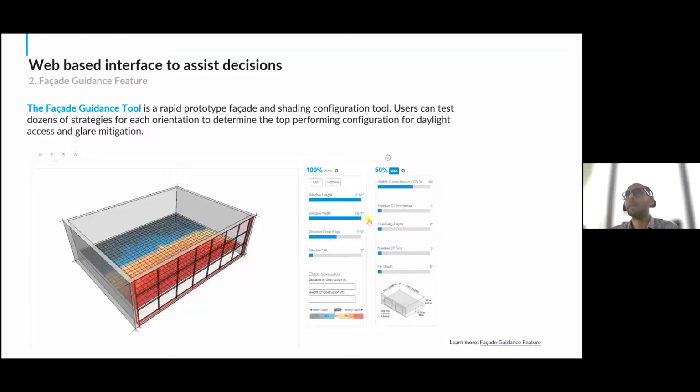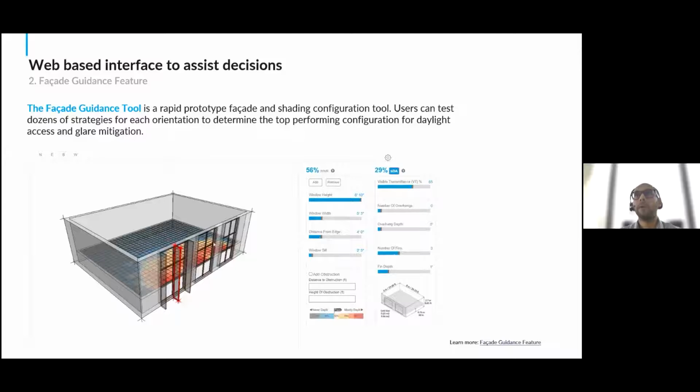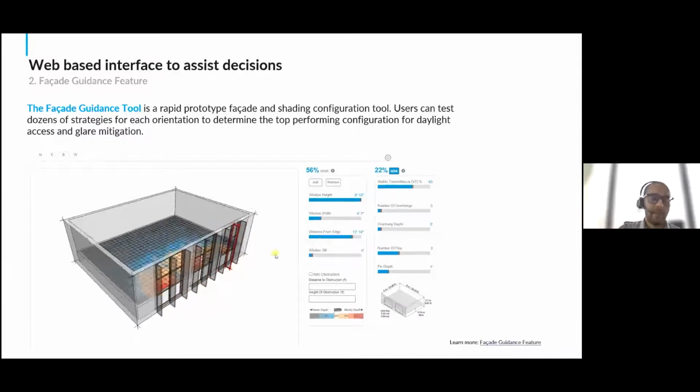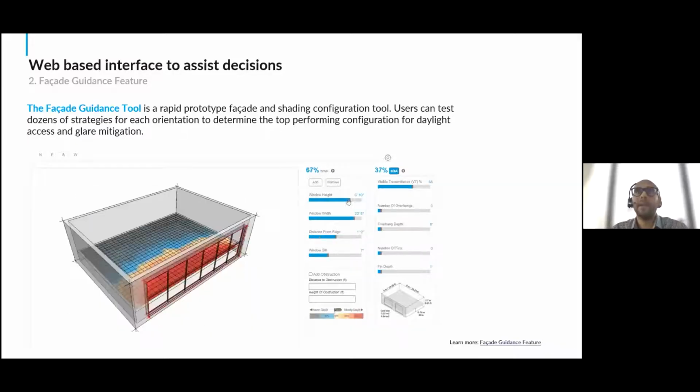So you might just go to the southern facade and say, we will try verticals versus horizontals. Similarly, we'll go for ribbon windows versus slit windows, and we'll see exactly what configuration leads to what kind of a performance. And then once we have found an effective strategy, we can actually go back to our original model with those strategies, because we are already educated in terms of what works and what doesn't work. So it saves you a lot of time modeling those objects, not validating after you've done the design, but being really proactive in terms of design.